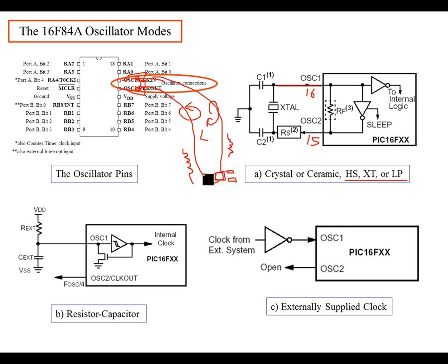Anytime you have a wire loop, the inductance is going to be proportional to the area of this loop. The area inside of that loop is going to be proportional to your inductance value. So if you want to eliminate that area, you could twist these wires together.